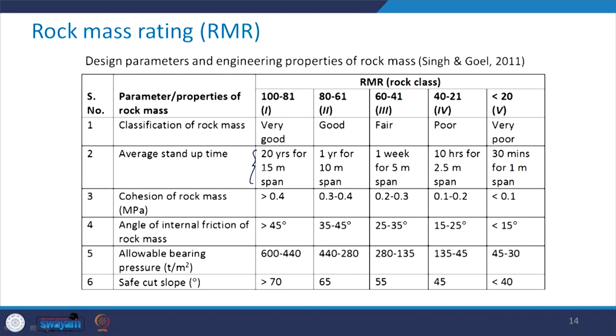Obviously, in case you have very good rock mass, you may have a very nominal requirement for the support system. This installation becomes quite crucial in case you have fair, poor or very poor quality rock mass, because you can see that here it is 1 week for 5 meter span, 10 hours for 2.5 meter span, and here it is only 30 minutes for 1 meter span.